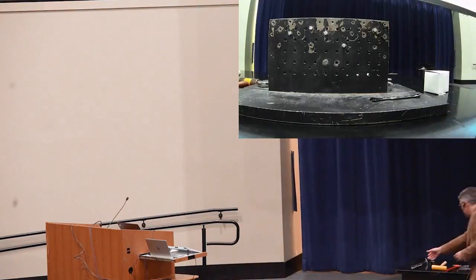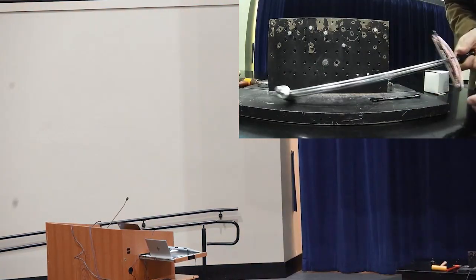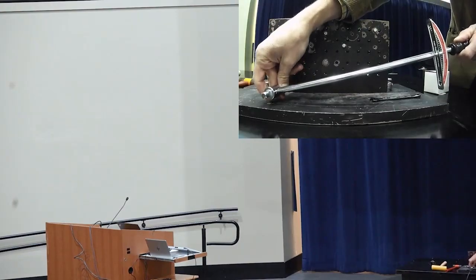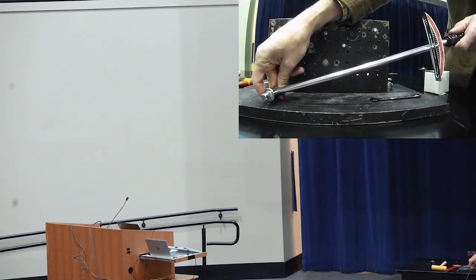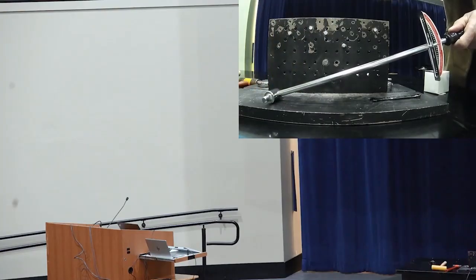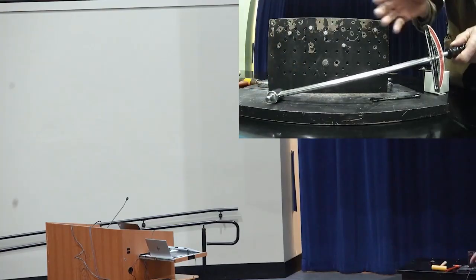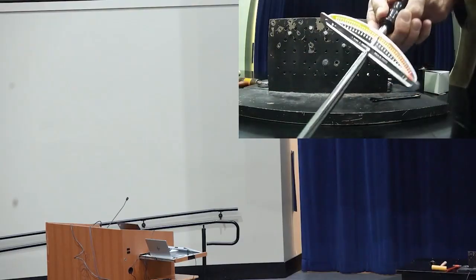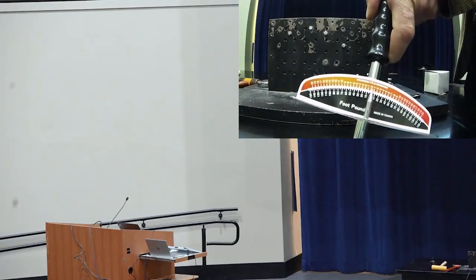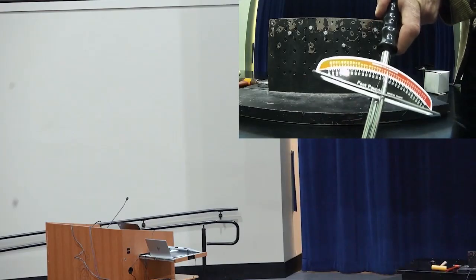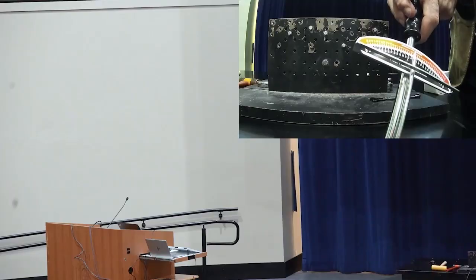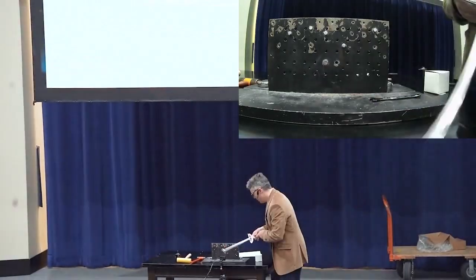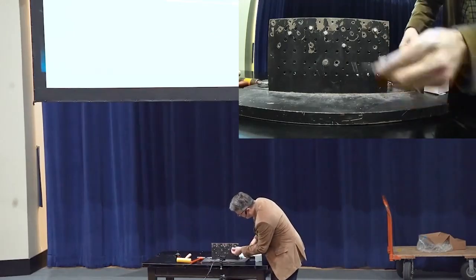So this is what's called a torque wrench. You can use this if you want to turn something. I think they use this for spark plugs a lot when you're installing a spark plug in a car. They want you to tighten it to a very specific torque. As you're tightening this, the dial actually shows you foot-pounds, but that can also be converted into newton-meters. A foot is a unit of distance, and a pound is a unit of force, so they call it foot-pounds.